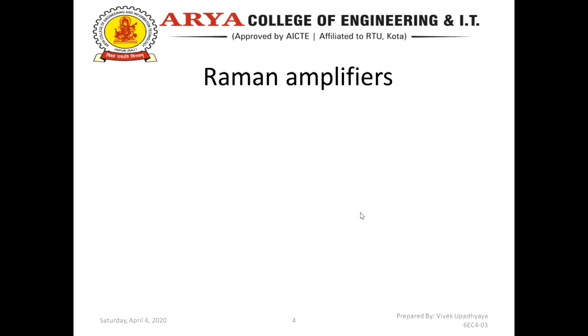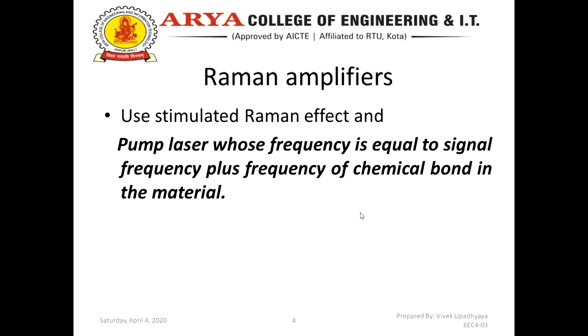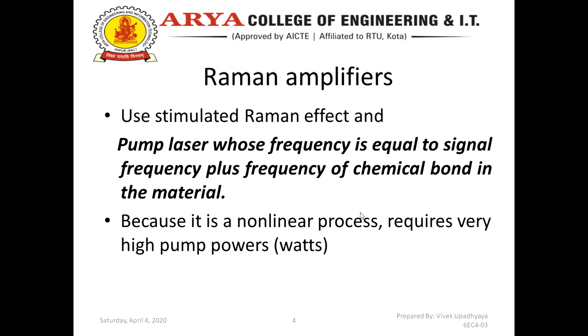Now the Raman amplifier uses the stimulated Raman effect and a pump laser whose frequency is equal to the signal frequency plus the frequency of a chemical bond in the material. And because it is a non-linear process, it requires very high pump powers, in watts.